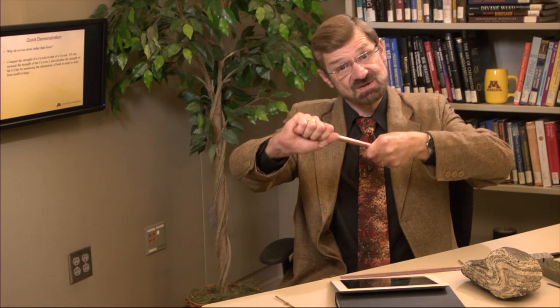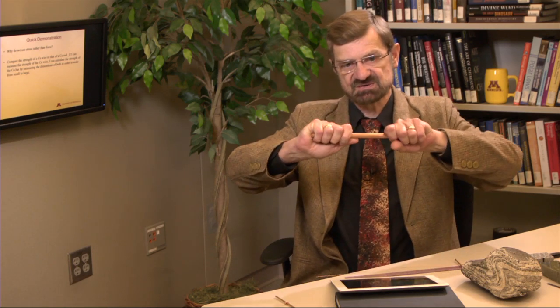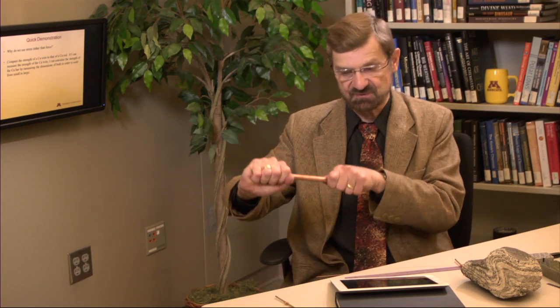And now, of course, I can take this rod and pull, and as hard as I pull, which is pretty hard, this rod will not get any longer. They're the same material, they have the same fundamental strengths, but because of the size, I need much greater force to deform this material, but I would need exactly the same stress to deform this large rod as I did to deform this fine wire.